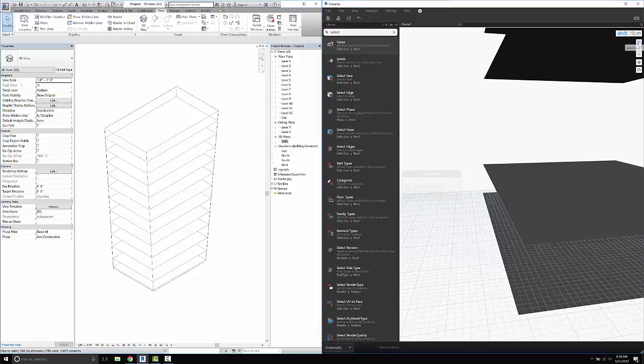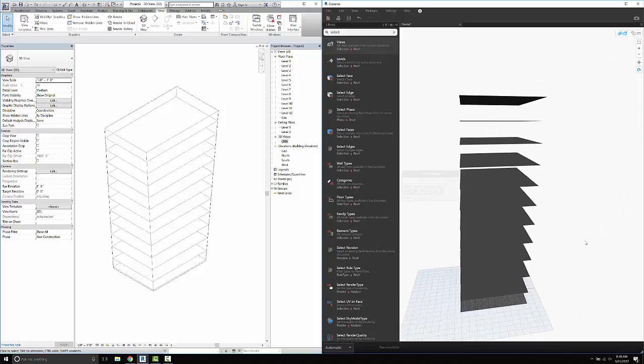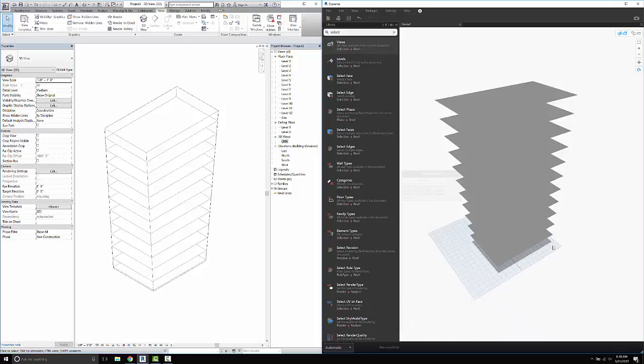I'm going to go to the geometry tab and then hit zoom to fit, and also hit the rotate so that I can pivot around this with the left mouse button and get a good view on all of my faces. So a lot of the components that we'll use in Dynamo aren't necessarily built right into the component. And there's a tab up here in Dynamo called Packages.